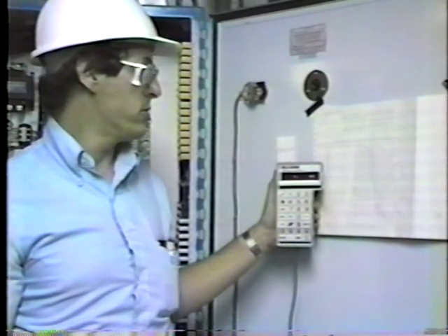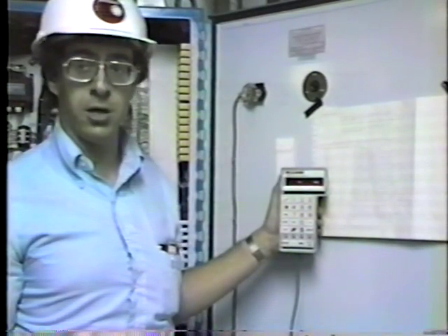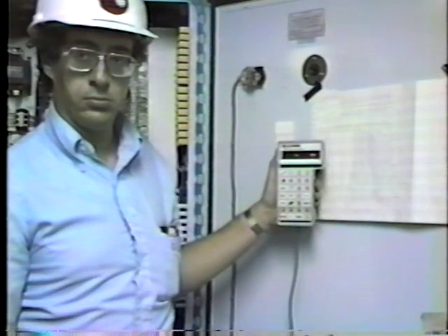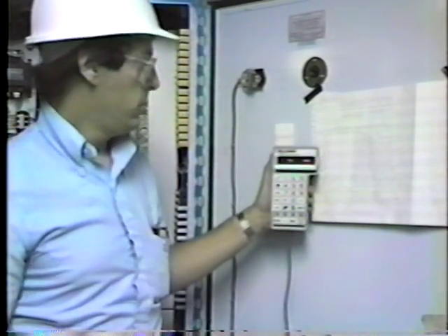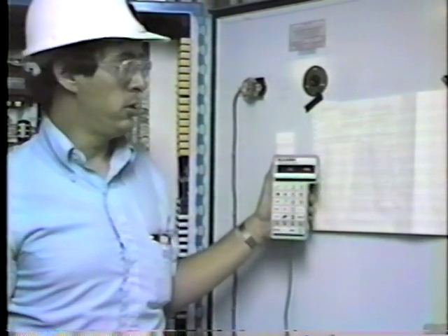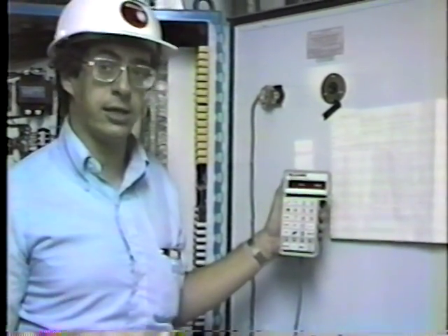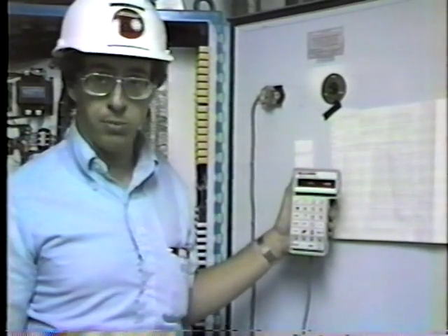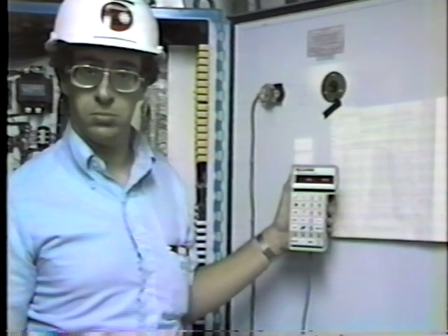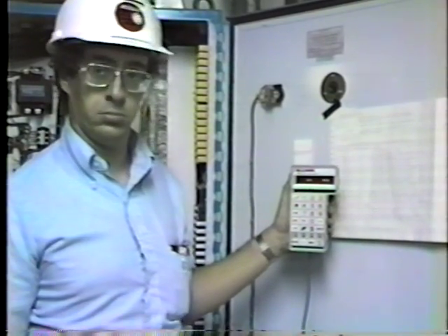Number 9 is the feeder speed minimum command. Again, we can command a minimum to the feeder of 0. And what do you have in there? It is 0. Okay. Step again. Number 10 is the maximum allowable milliamps at minimum mill speed. This parameter allows us to set the computer for the wear alarm so that we can detect journal or bearing wear problems. Okay, this has not at this time been set because we do not believe that the mill has been run in properly to determine how that should be set as yet. That will be set later on.